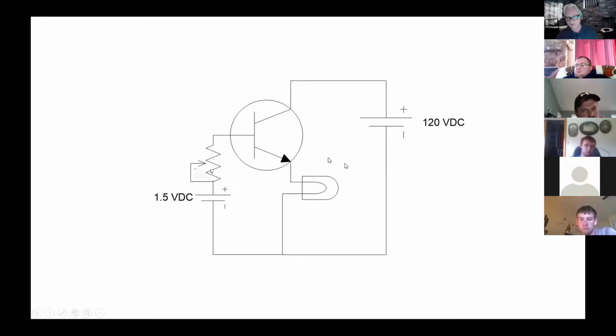It's dim, it's cool, it's slow, whatever the load is. But as I increase the current going into the base, so does the collector emitter current increase. So I can vary my output with a transistor. Think of a spigot, a valve. I can turn it all the way off and all the way on if I want all or nothing. I can do that real quick, and if I'm doing that, that's essentially switch action. But most of the time when I'm operating a valve, I'm trying to adjust it to get the optimum amount of flow that I need, and that's what's happening whenever I do this.